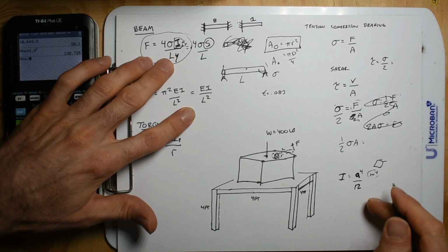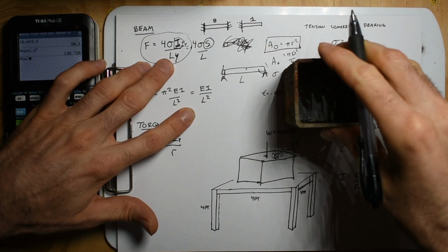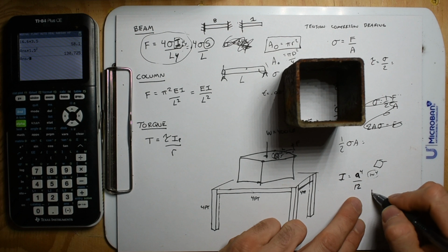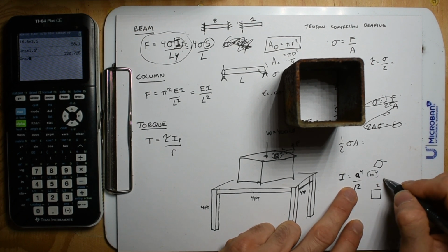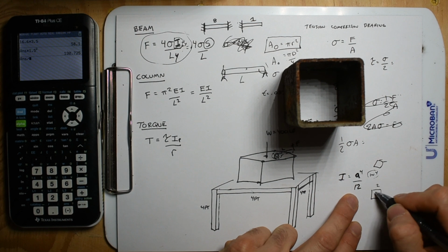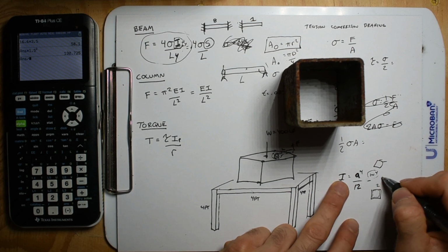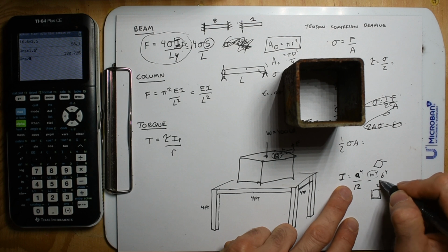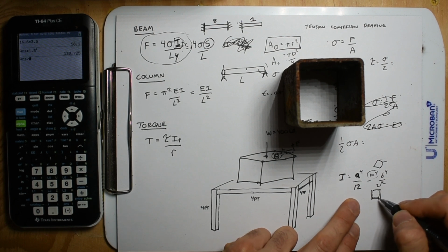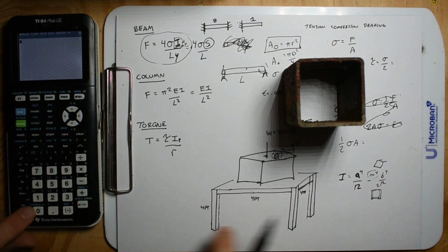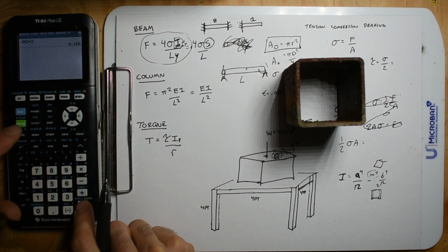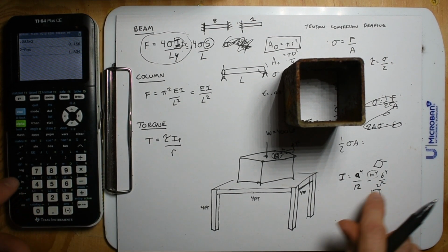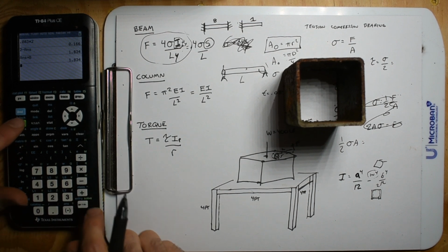If we have something that looks like this, you take the outside diameter, 2, so it's 2 to the 4th divided by 12, but then there is no inside part, so you have to subtract that, maybe b to the 4th divided by 12. If the thickness is 0.083 times 2, then we go 2 minus that. Now we have this stored as alpha b.